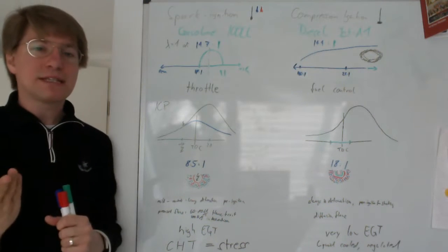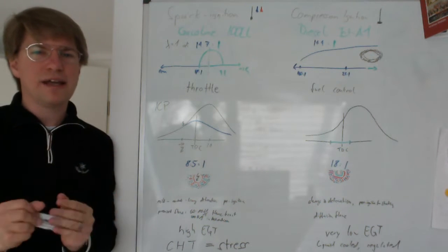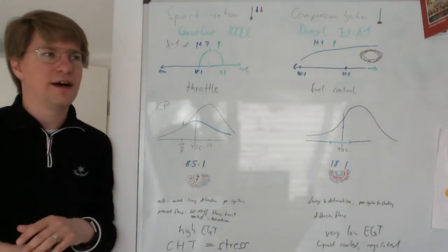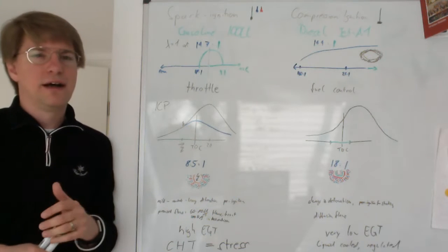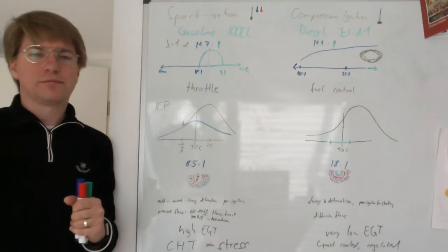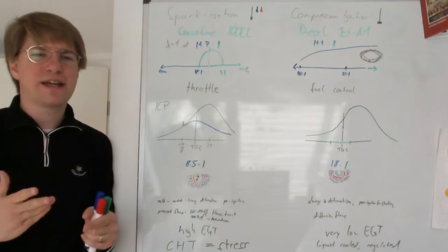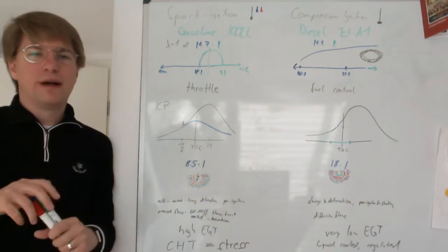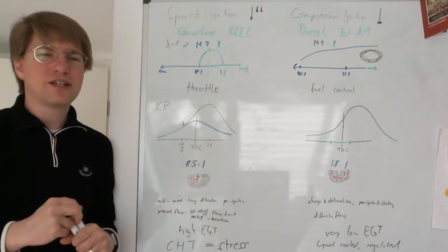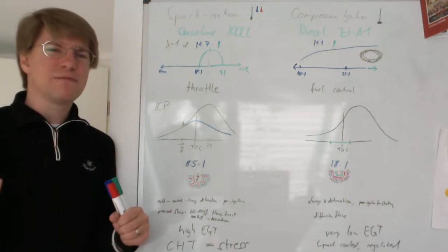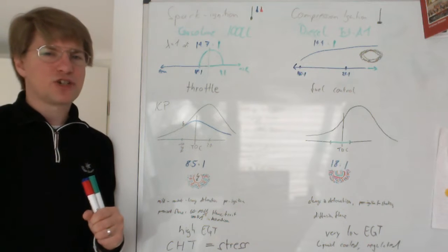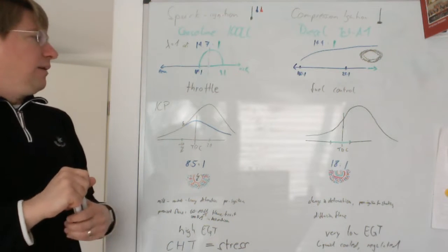So that's why it makes sense to have an intercooler, or an air-to-air intercooler, which most modern turbo-normalized engines, such as the TIO-550 Continental, have: dual turbochargers and dual intercoolers to offset this effect of the air getting too hot. So with a turbo normalized and intercooled engine, we also don't need to tweak the mixture control very much as we climb, because the air pressure stays high.